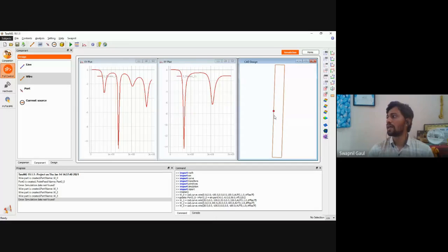As we know, there is an impedance mismatch. The impedance mismatch is because the port impedance is not equal to the input impedance of the antenna, and when we make these two equal, we will have better performance. To match this impedance, there is an analytical formula in the textbook for the n-element folded dipole antenna. The formula is Zn equals n squared Z0, the number of elements squared times Z0.